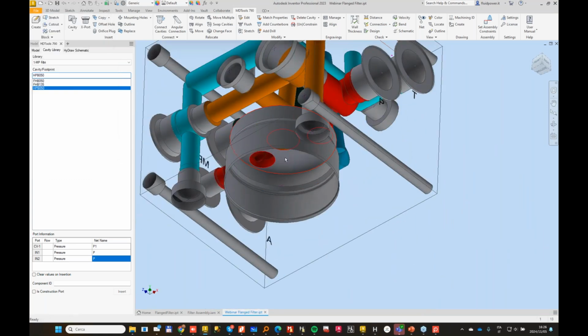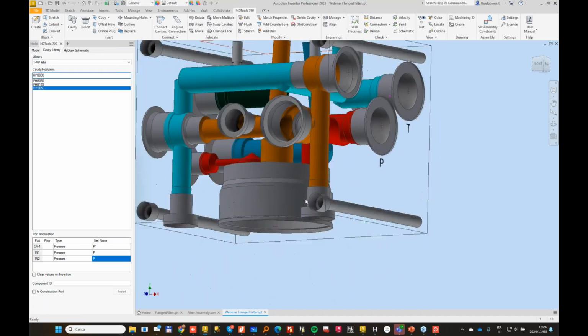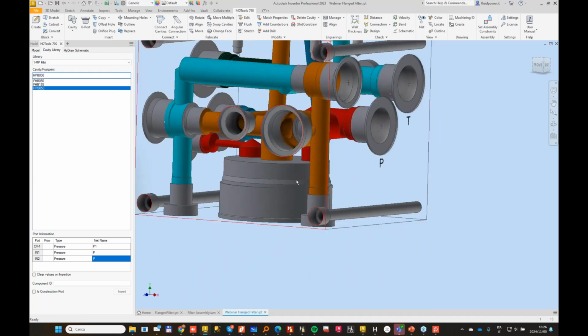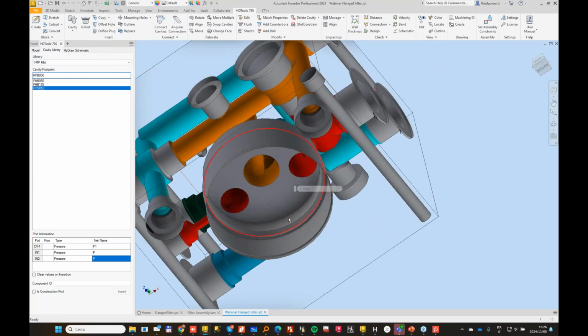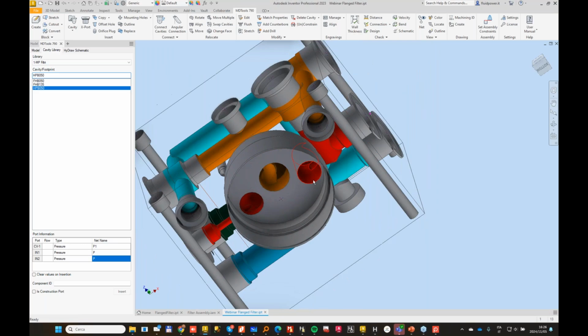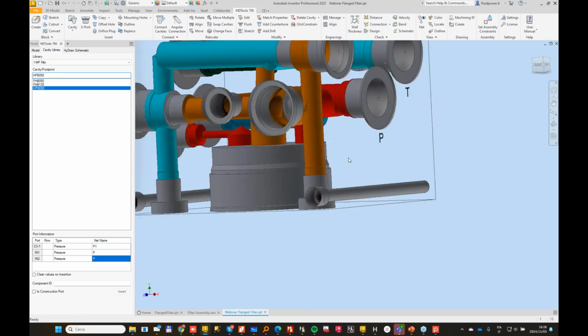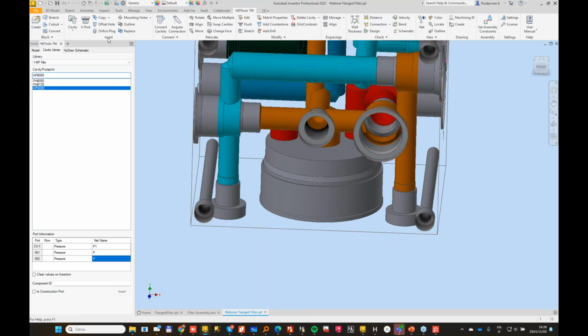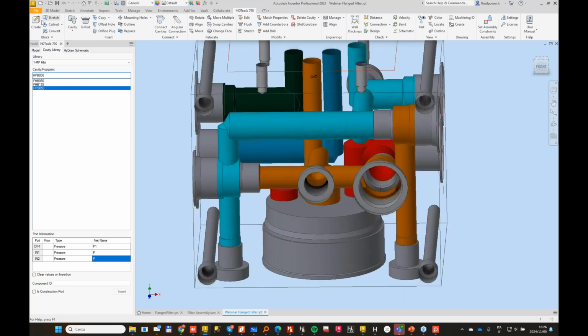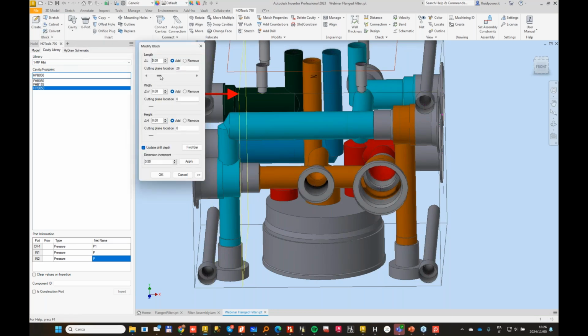Of course, this cavity will be expensive because the flanged filter requires just 2 bolts and 2 drills. This requires special tooling or attention, but in this case, the benefit will be good volume saving. I can also remove some material on the length here. Let me remove maybe 5 millimeters.